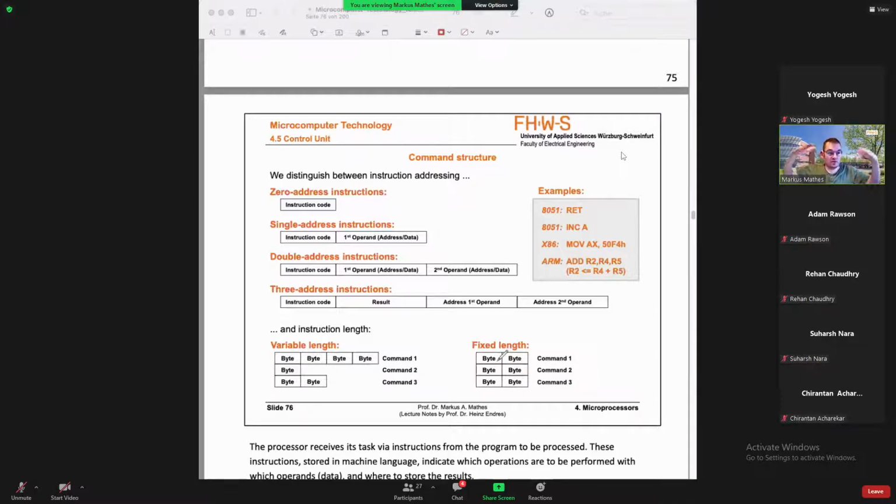So in your program code, each instruction is stored with 2 bytes. And if the width of your main memory is 1 byte, that means you need 2 lines per instruction. And your program counter is incremented by 2 after execution, right? So you always go 2 lines ahead.